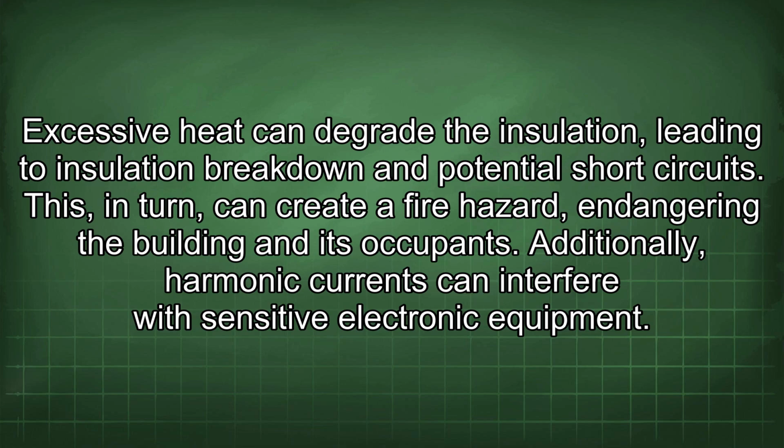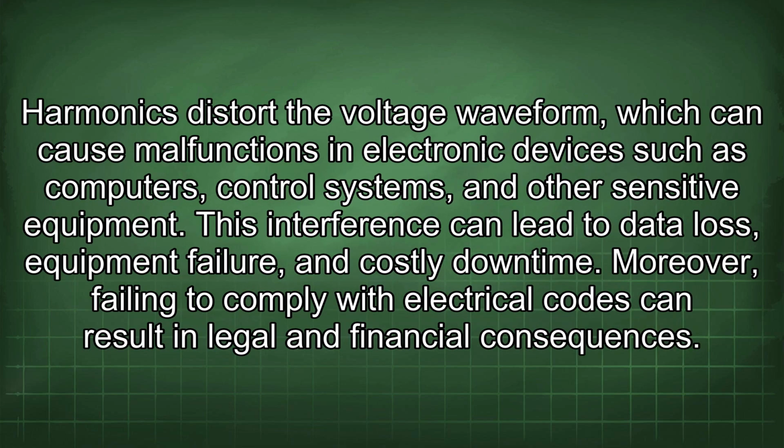Additionally, harmonic currents can interfere with sensitive electronic equipment. Harmonics distort the voltage waveform, which can cause malfunctions in electronic devices such as computers, control systems, and other sensitive equipment. This interference can lead to data loss, equipment failure, and costly downtime.